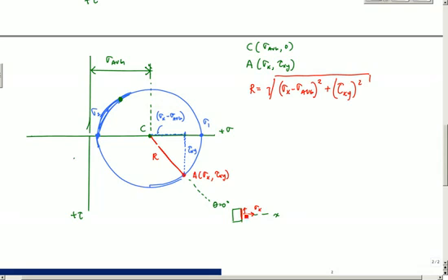And if I go all the way to the other side over here, based on equilibrium, you know that this right here is also sigma x, and this should also be tau xy. So if I go all the way to the other side, which in real life would be a rotation of 180 degrees, that 180 degrees is essentially going back to the same state of stress.